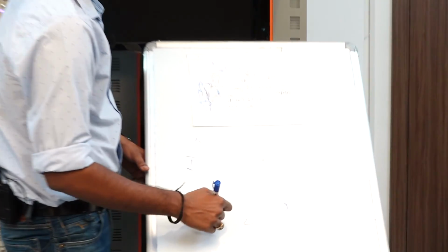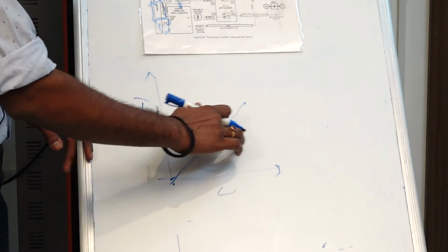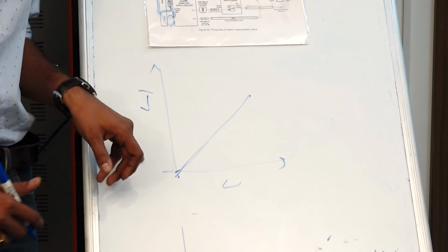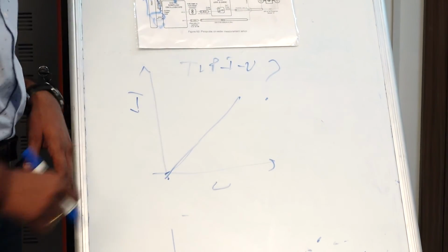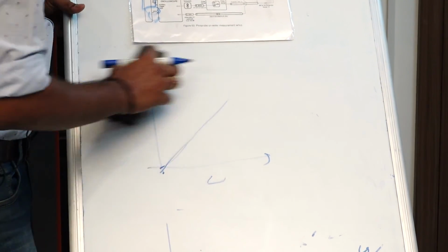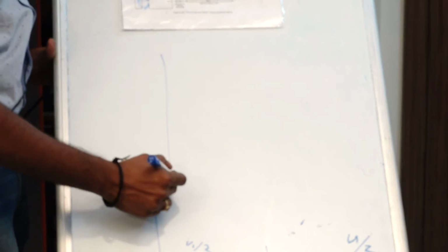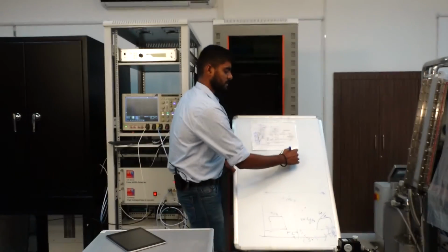which look like this, or which may have any weird shape possible for different devices. But you would see a lot of IV characteristics called the TLP IV characteristic. Where do these come from? Now, these come from a very interesting thing that we do. Whenever you capture a voltage and current waveform, so this can be V or I as a function of time, and this is oscilloscope measurements.